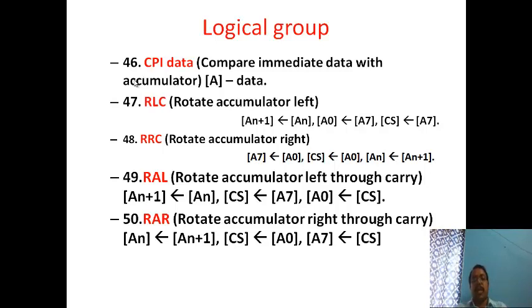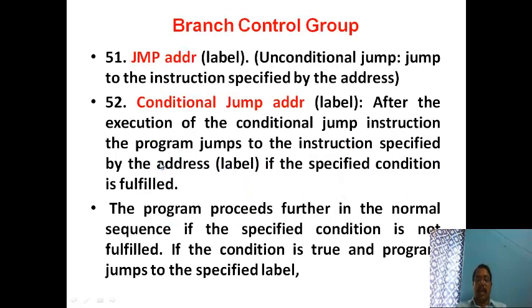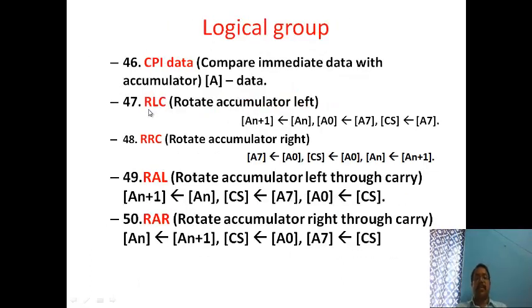You can rotate left your 8-bit, or you can rotate right your 8-bit. 8-bit is nothing but the 8-bit value in your accumulator. So rotate left. See, there is again a flaw in 8085, the notation they have wrongly done. Please see here, RLC, you should not confuse that it is rotating left with the carry. Without carry means there will be a C. If you are involving the carry, then C is absent. So this they might have wrongly used. If they put the C here, then it would be very easy to remember rotate with carry and rotate without carry, but that is not there here.